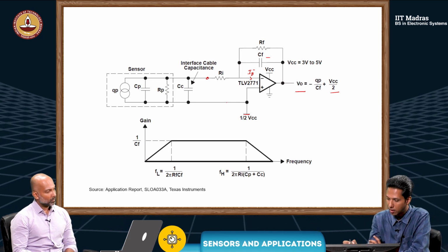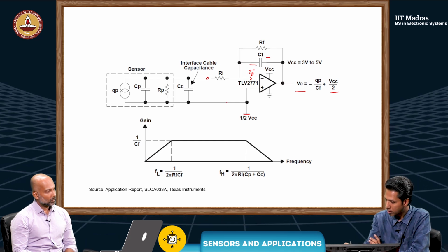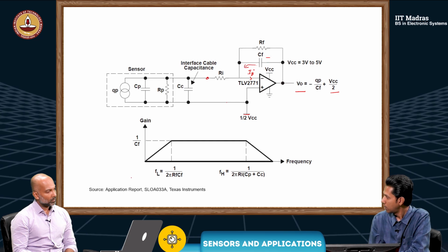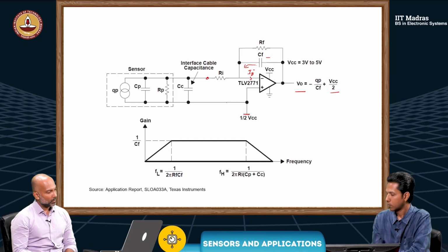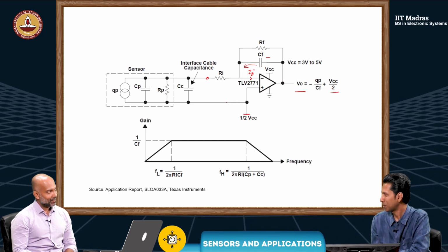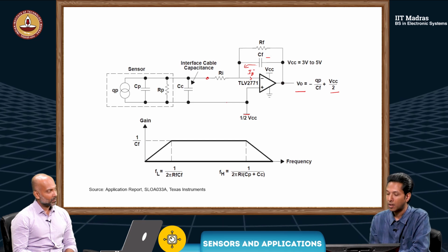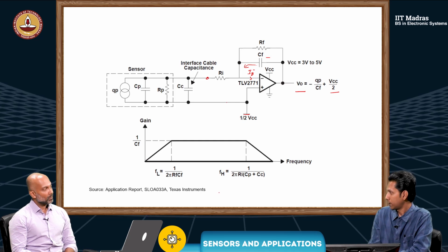Now, this current has to come from the output. If you have only this capacitor, it will come through that, and once you turn on the op amp, it will always keep flowing. So, it will charge the capacitor and go to saturation in milliseconds, depending on the capacitance value and bias current. So, you cannot actually use it.